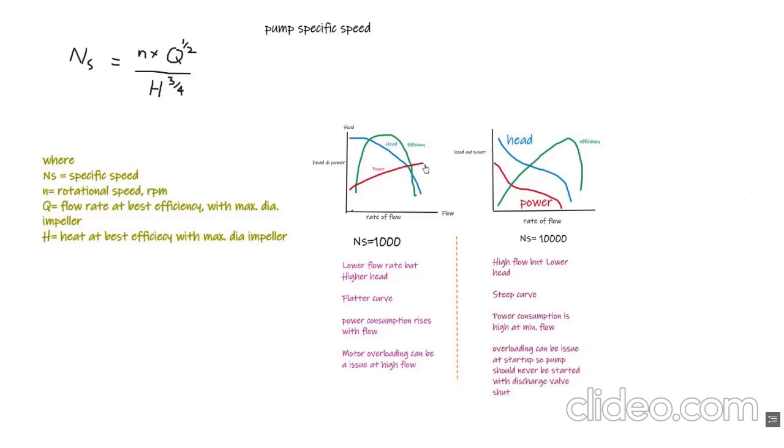The designer should take care of this aspect during selection of pump and motor. But for the high specific speed pumps, overloading can be the issue at startup.